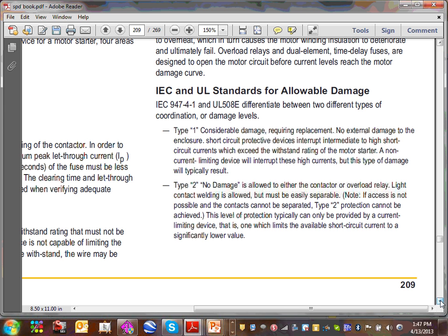Type 2, you have a ground fault or a short circuit on the load side of the motor controller. All you have to do is fix the problem first. Why are we ground faulted? Why do we have a ground fault, or why do we have a short circuit? When you're done fixing the motor and found the reason for the ground fault, then you're supposed to change your fuses. Typically, it has to be fuses, and everything should be okay. You might have minor damage in certain equipment, but your equipment might survive. Anyway, so that's this one.